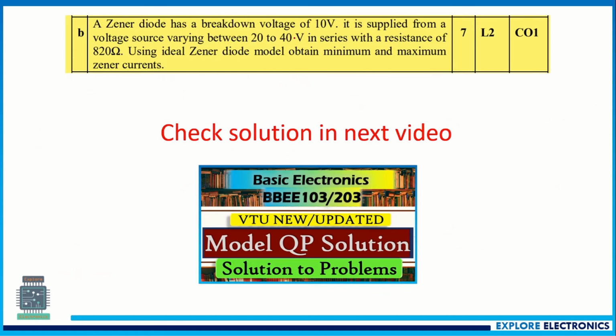Here is the problem on Zener diode. They have given the source voltage which is varying from 20 to 40 volts and the breakdown voltage of the diode is 10 volts, and they have also given the input resistance, that is 820 ohms. We need to find the minimum and maximum Zener currents. This problem's solution is explained in the next video. This is the thumbnail of that next video, solution to problems. You can see the solution over there.